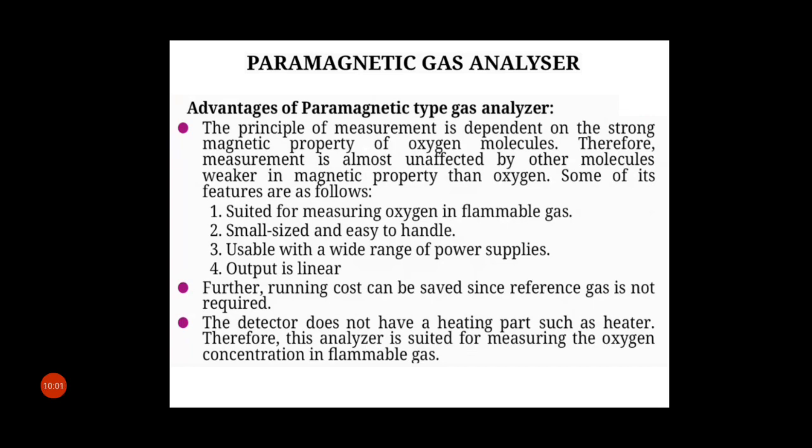First, it is suited for measuring oxygen in flammable gas. Second, it is small sized and easy to handle. Third, it is usable with a wide range of power supply and its output is linear. Further, running cost can be saved since reference gas is not required. And another one is that the detector does not have a heating part such as a heater.